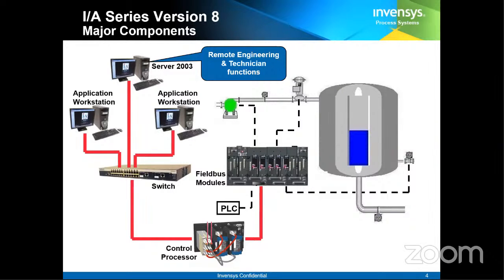That's why we call it a distributed control system, because the whole control system is able to distribute itself in the whole plant. In the case of Foxboro, this is one control processor. Its capacity does not depend upon the number of inputs or outputs. It depends on how many blocks it can keep inside its memory.